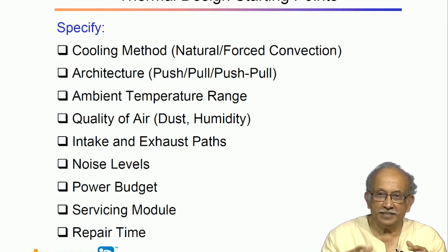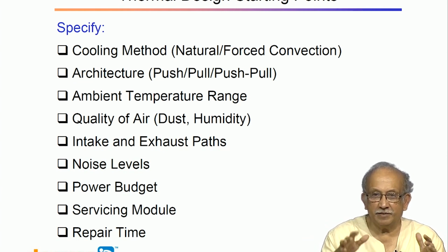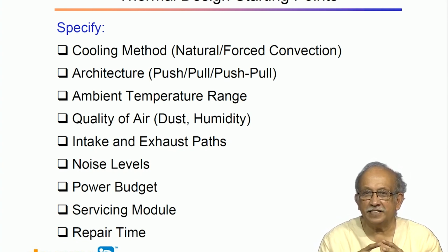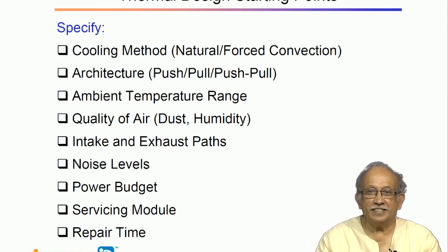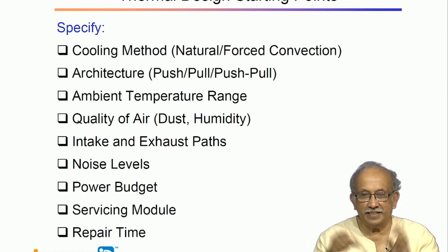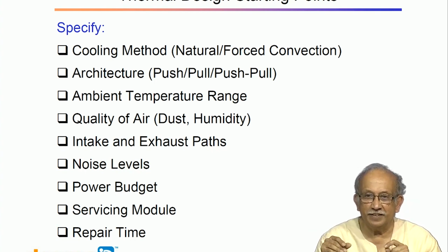So, ideally I think people enjoy around 22, 23 degrees. At that point if it is humid, water will start condensing on the sides of the refrigerator, and if you take the old type of mineral wool insulation, soon the insulation gets waterlogged.